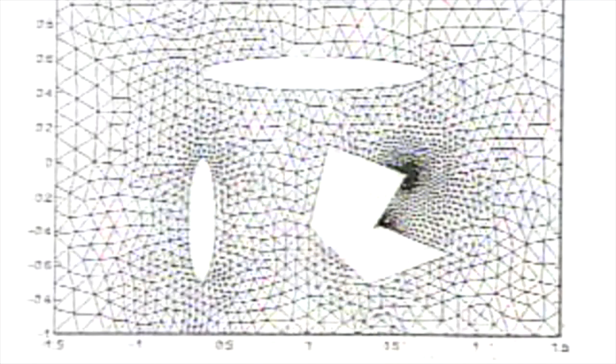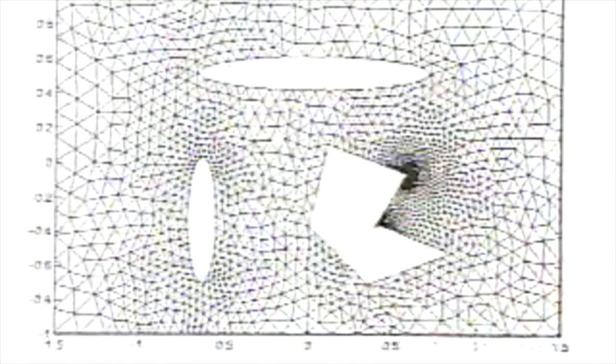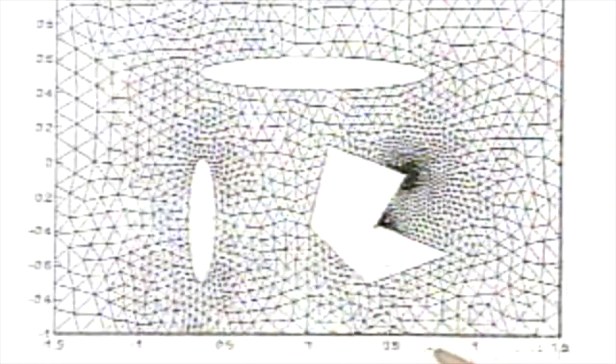Here's the triangles everywhere. Now the interesting thing you'll notice about this package, what a lot of them do automatically, is where you get corners and edges, turning points, you get better resolution. So a lot of these packages automatically account for the fact that you have a region of rapid transition here, here, on these corners here, and then it makes smaller triangles here, but over here where nothing much is going on, around these edges, pretty big triangles.